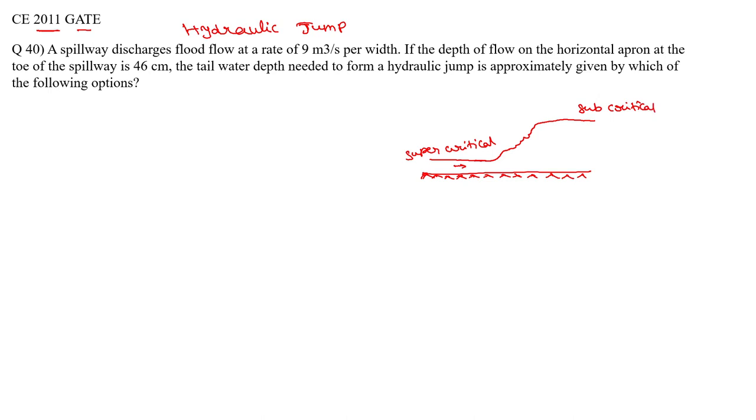So when the flow takes place from the low pressure zone to the high pressure zone, the hydraulic jump takes place. And we even discussed the main three equations. One is that y2 divided by y1 equals 1 by 2 square root of 1 plus 8 F1 square minus 1. I hope you remember this particular equation.